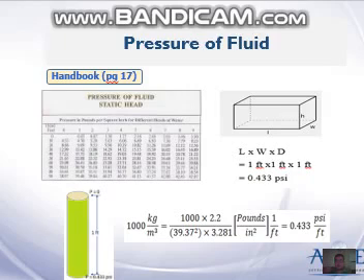Pressure of fluid. Pressure and depth is the fundamental relationship in the oil industry. The easiest way to calculate pressure from depth is to use the pressure gradient of the given fluid. To find the pressure per square inch for any feet of head not given in the table above, multiply the feet times 0.433. 0.433 is the gradient for pure water, SG equals 1, specific gravity, in imperial units. Remember it?